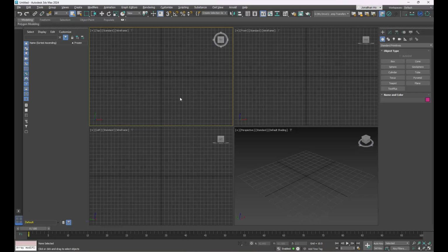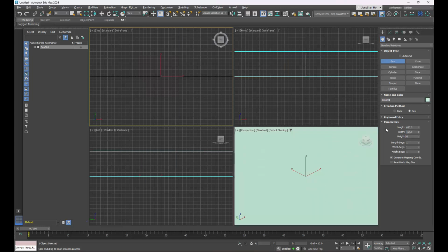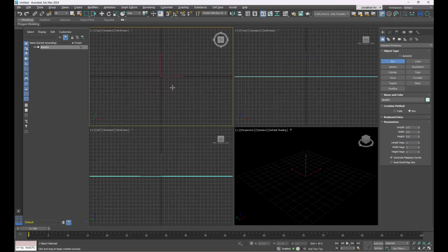what I tend to want to do in general is I like to have an overall idea of how big I'm modeling anything at all. So generally I will start with a box first, and I'll create a box with a certain dimension. I know that a chair usually does not get bigger than 450 by 450, so I will start by modeling a box 450, 450, 450 first.